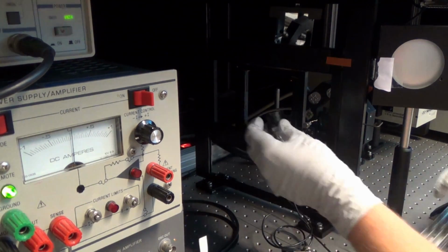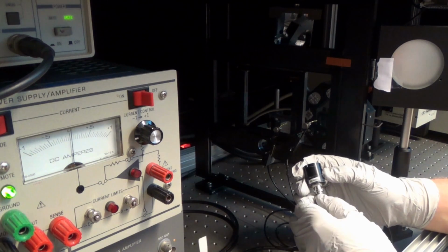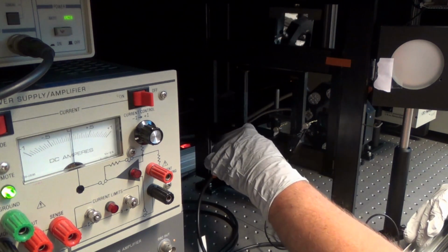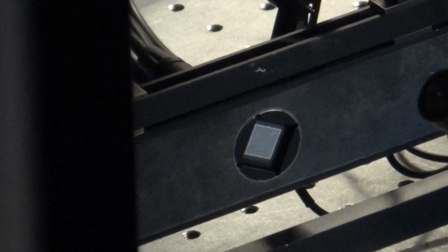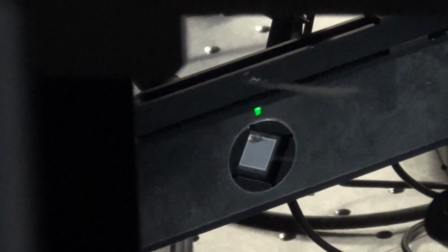Before we can take the actual measurement, we will first connect a calibrated silicon reference diode and place it in the probing light beam. This diode will precisely measure the photon flux of the light source at each wavelength step. The light spot is green before the measurement for good visibility.